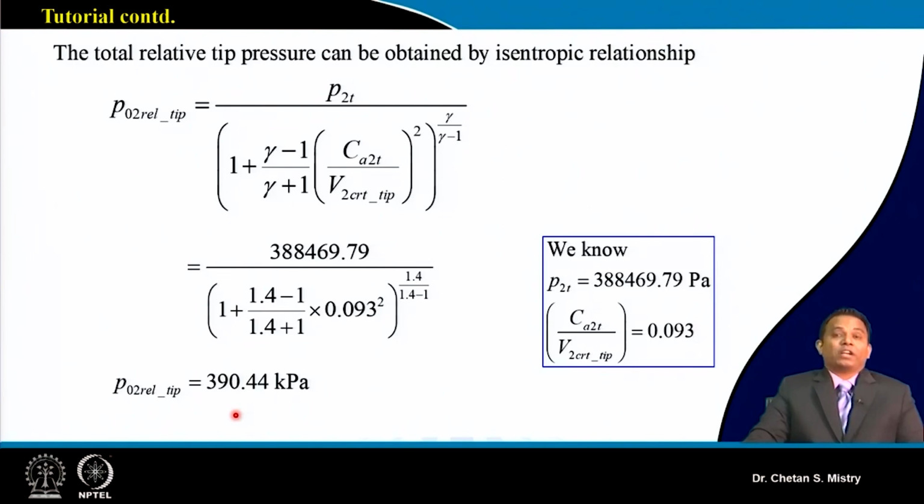By using that data, maybe you can calculate what my total pressure ratio or my overall pressure ratio needs to be, and what my temperature needs to be. If that temperature is off, it indicates that something is wrong. So that's how we need to apply what we understand from our basic learning in fundamental courses, and this is what comes as the applied part.